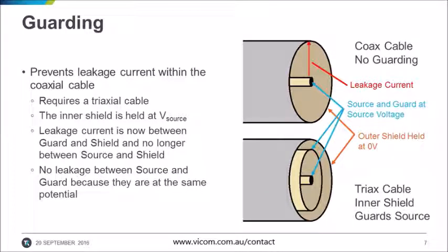For high resistance or high voltage measurements, we need to take cable leakage into consideration. Inside of a coaxial cable, we have a rather large but finite impedance between the conductor and the shield.